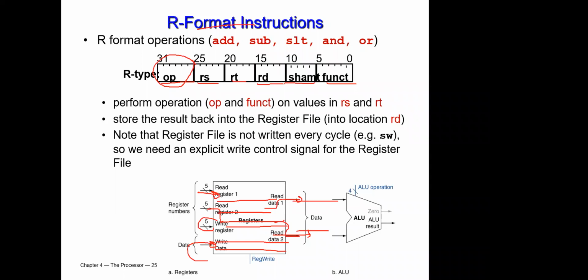After I have this, now this ALU will do a certain particular instruction. Either I will do addition, multiplication, division, whatever it is, and the command will come from here, the ALU operation. Meaning there is a signal input to the ALU that will inform the ALU what exactly to do. How will I get these results? ALU operation, of course, after I decode the function, I will know, for instance, that I have to do addition, or subtraction, or whatever I need to do with this particular R-type instruction. And it will inform the ALU what exactly it needs to do.